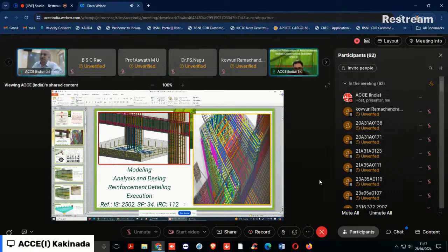This is a cantilever flexural bending moment in the upward direction with the tension plane at the bottom. It has an anchorage length beyond this critical section for the bending moment, starting from this 40 mm from the stirrup of the column, and it should have a development length. If the straight development length is not sufficient, only then do we have to bend it into an L-shaped bend. Otherwise, it is not required. A simple straight bar is required. But as a general rule of thumb, we put an L bend in all footings.